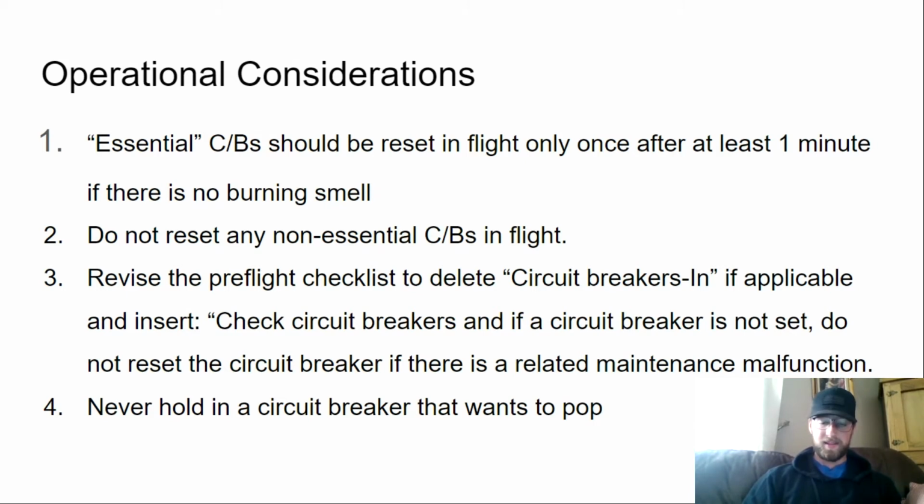Third one, revise the pre-flight checklist to delete circuit breakers in. So when we're going through a pre-flight check and it tells us to check the circuit breakers, if there's a circuit breaker that's popped, don't reset that circuit breaker if there's a related maintenance malfunction. Get a mechanic and have them look at it.